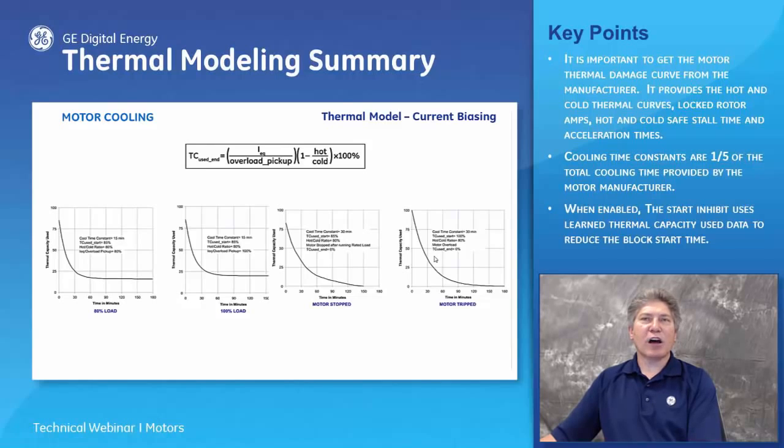When the I equivalent is higher than the overload pickup level, the motor is heating. If the I equivalent is lower than the overload pickup level, the motor is cooling.